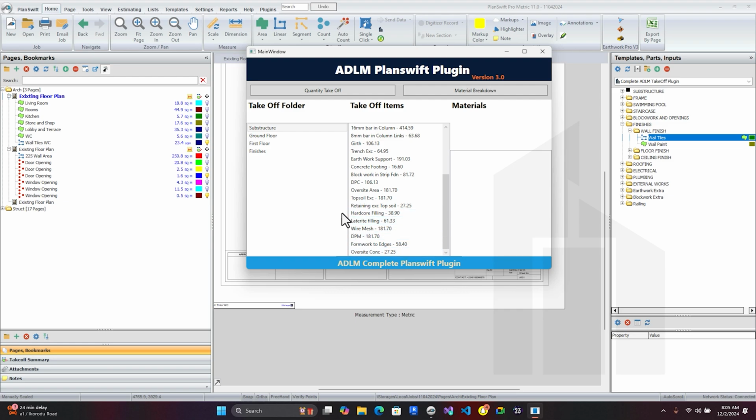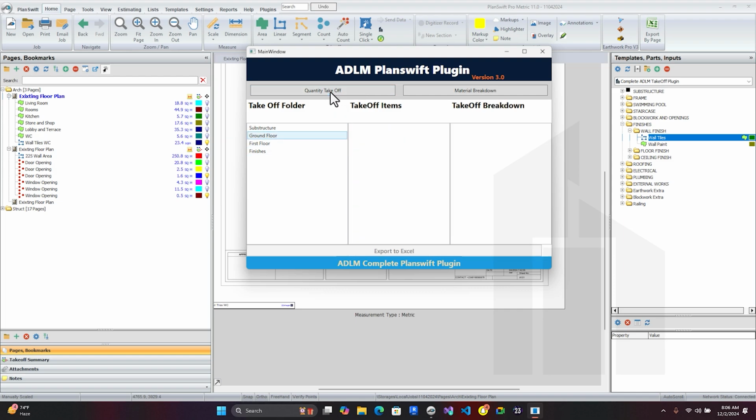Okay. Now we check out ground floor area. Also, you check out ground floor. This feature is also there. You select the walls. You see walls. You have your block. For this, you have the total blocks you need, total cement you need, and total sand you need for completing that particular work. Concrete, you click calculate. You have your number of cement, sand, and granite you need to finish up this concrete work. Form work, you have the material needed, and you have your doors, your window and door schedule. So you have come to takeoff view here, and easily view your window and door schedule.